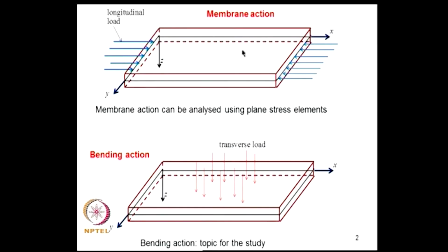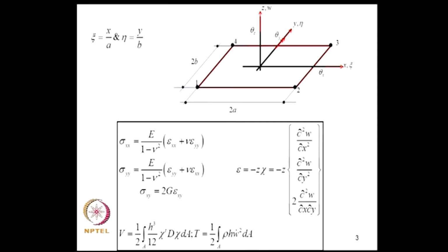So, plates carrying forces in their own plane are said to behave like a membrane, whereas if the structure carries loads transverse to its middle surface as shown here, the plate would bend, and this is known as bending action. So, right now we are focusing on analysis of the bending action. If the membrane action has to be studied, the plane stress elements that we have developed earlier can be employed. Now, in the last class we formulated a few details.